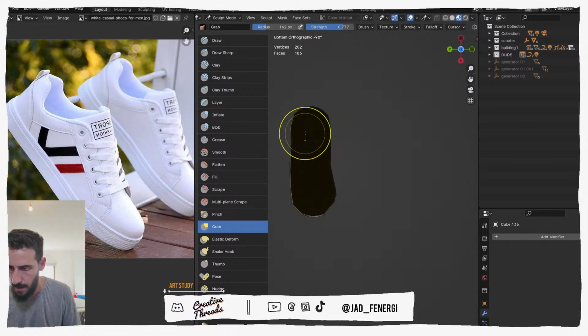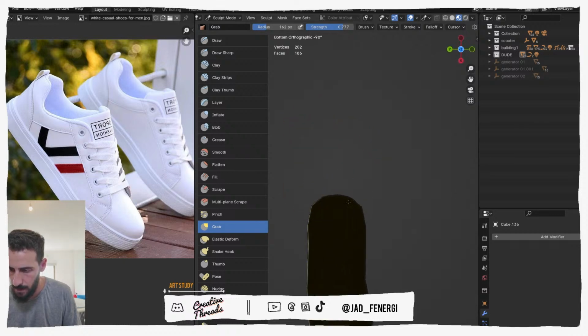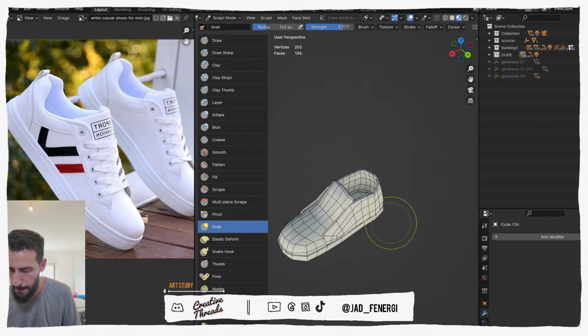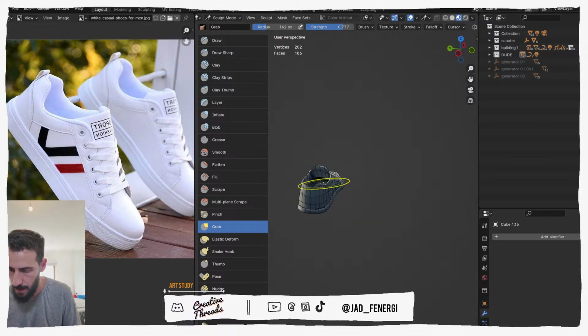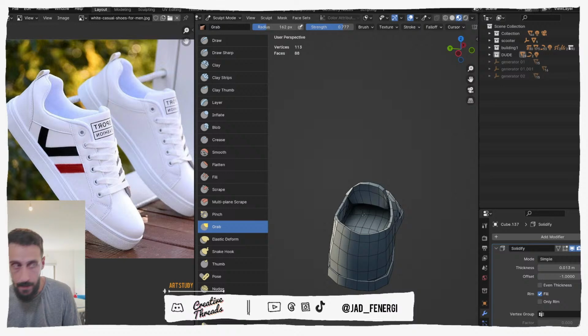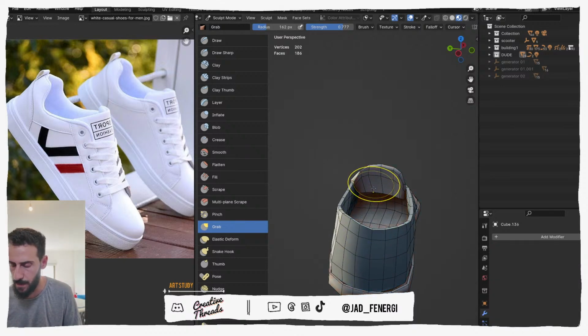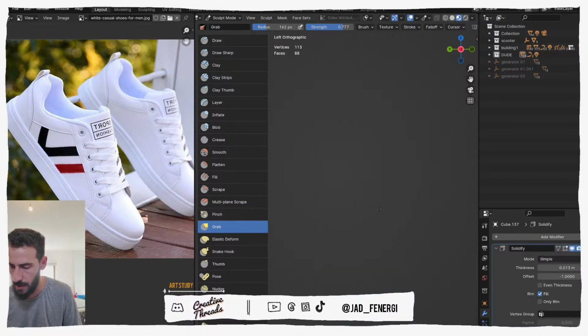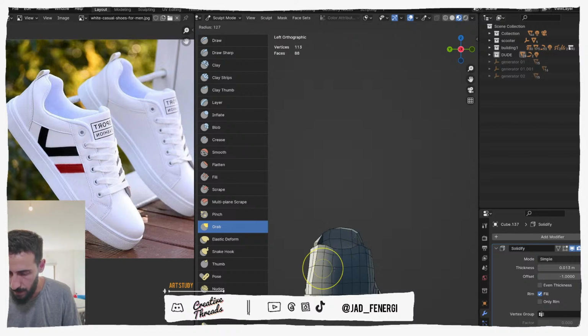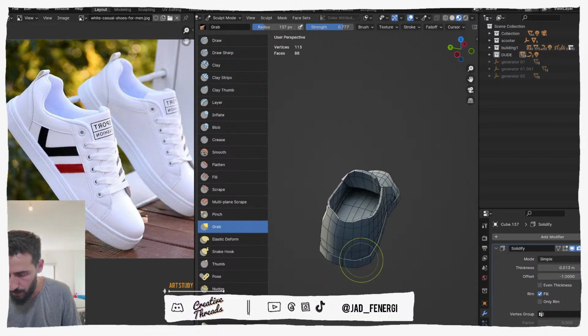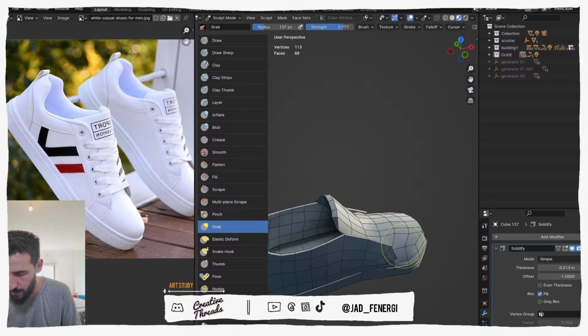And down here it is looking fine. Alt Q: you just hover above an object and press Alt Q to change the selection while you're still in sculpting mode or edit mode or texture mode or whatever you are in. You don't have to go in and out of object mode, just press Alt Q. You'll save yourself some time.